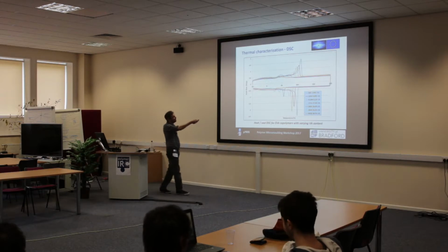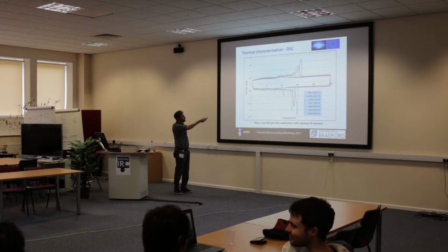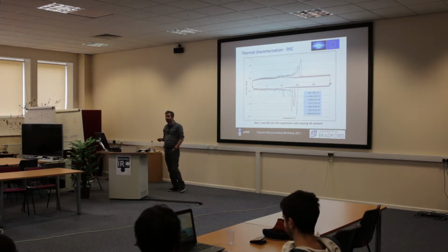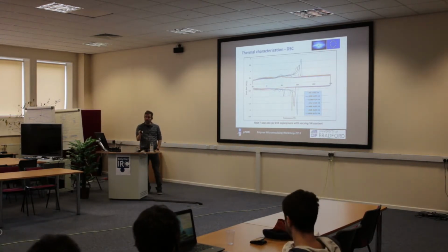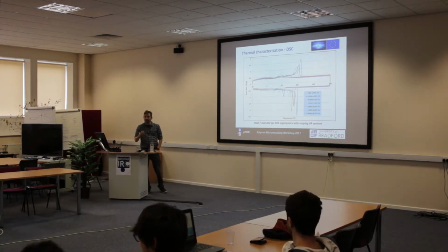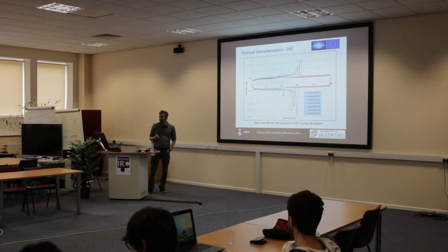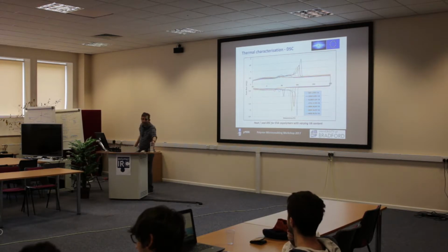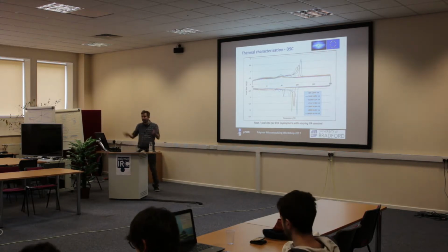With this material here, we can process at about 90 degrees C. With this material here, we can process at about 130, 140 degrees C. So the energy we require to put into our process, which can be huge, we can reduce massively as well. And this is one of the big advantages of polymers in the first place. This is why this bottle is no longer made of glass. It's now made of plastic because it processes at about 280, whereas glass processes at 700, 800 degrees C. So the energy usage is massive.